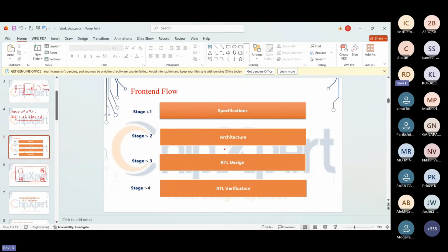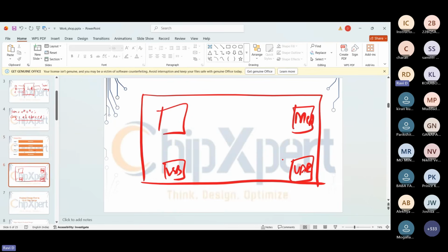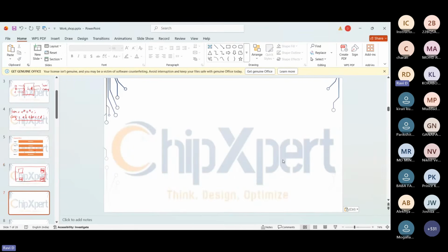And the third stage is the code. After designing the architecture, we are going to write the code. We design the code in Verilog language, as mostly we use Verilog to design circuits. Why Verilog? Most industries use it, and it is easy to synthesize. Verilog is easy to learn and easy to synthesize your design, and it provides that flexibility.